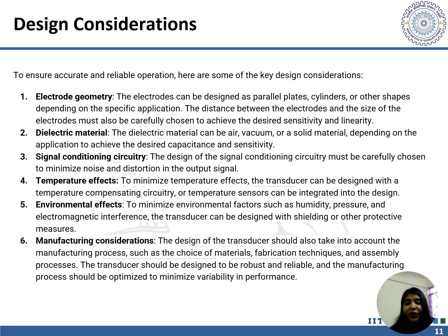Now let's move on to the next part of the presentation, which is the design considerations. Some of the key design considerations that we should make to ensure an accurate and reliable operation of the devices. First is the electrode geometry. Electrodes can be designed as parallel plates, cylinders, or maybe in other geometric shapes depending on the specific application. The distance between the electrodes and the size of the electrodes should be chosen very carefully to achieve the desired sensitivity and linearity.